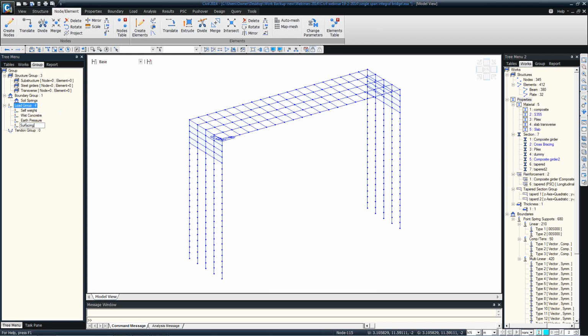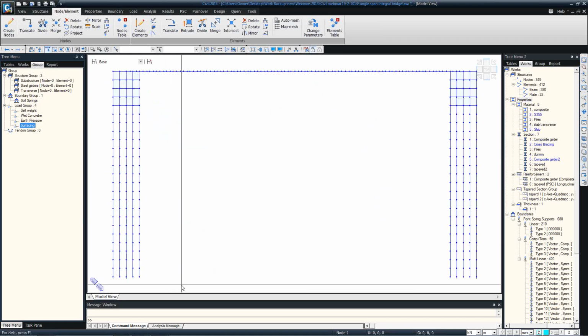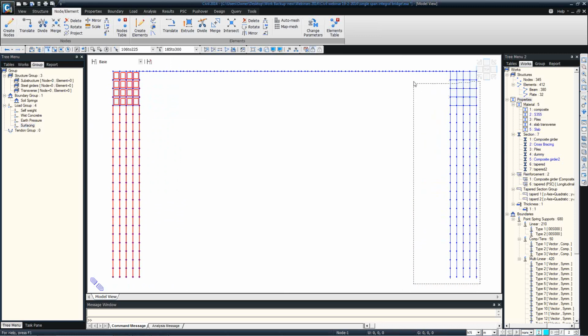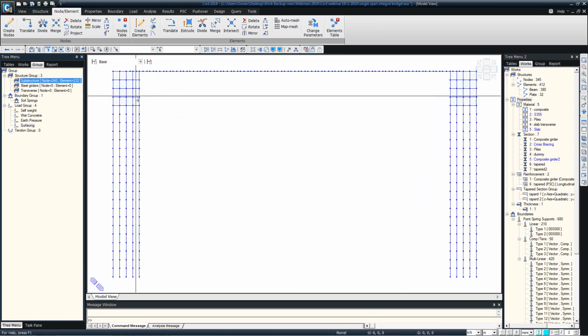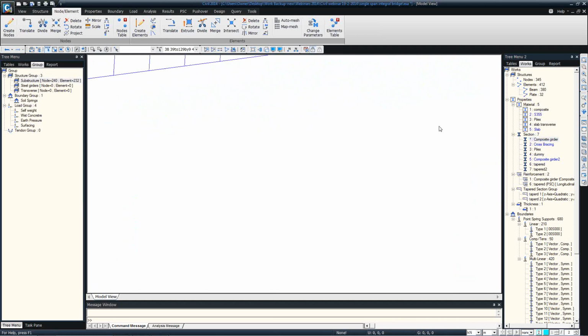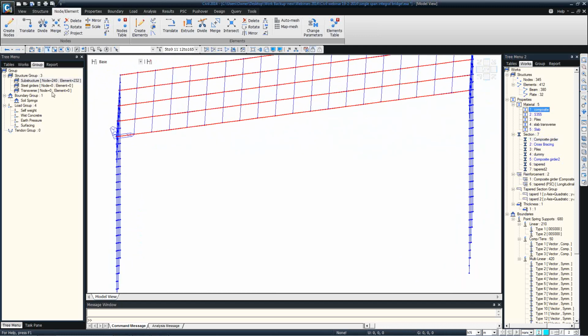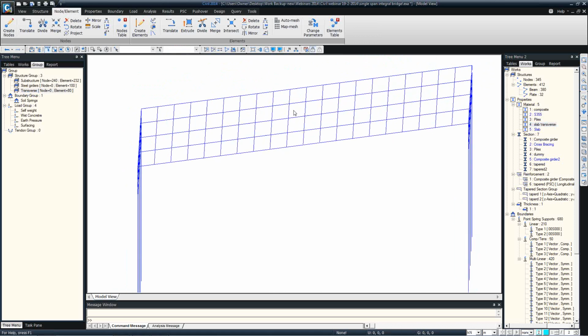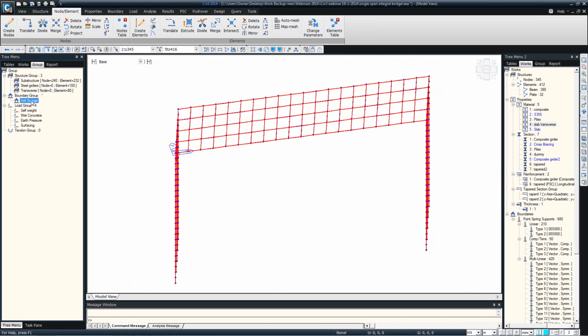Okay. Now quickly I'll assign different types of elements to groups. I'll start with the piles and abutment first. So just quickly copying all the piles and abutments and drag and drop into substructure. All the steel girders, so double click on the composite material and drag and drop into steel girders, and double click on slab transverse, drag and drop the transverse members. Then select everything, drag and drop soil springs to include all the boundaries in the structure into the soil springs group. And for self weight and wet concrete, we'll see when we apply the loads.